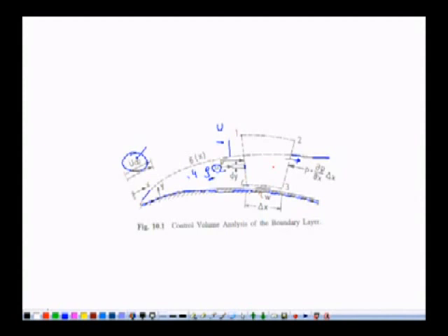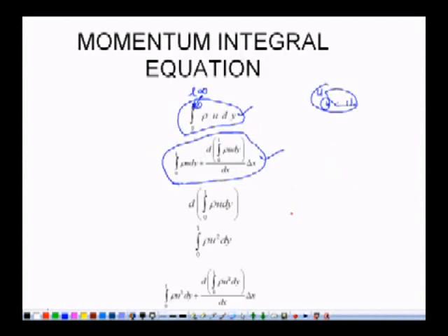And since the flow is steady, inside the control volume the rate of change of density or rate of change of mass must be 0. So whatever mass goes outside the control volume through face 2, 3 must be coming from 1, 4 and 1, 2. Right. With the help of this concept, we can write the continuity equation.